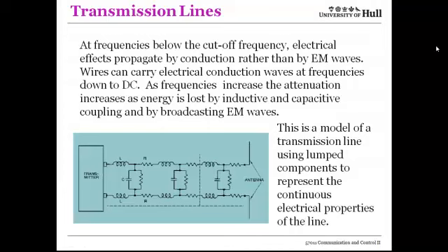Electromagnetic signals can propagate in one of two different ways. Either we can be dealing with an electromagnetic wave like light or a radio wave, which can propagate best through a pure insulator, or it is a conduction wave. It's a wave of movement of a concentrated area of charge, generally carried by electrons, and so you get a compression wave of electrons travelling along a conductor, and the more conductive it is, the better. Now at high frequencies, signals tend to propagate predominantly as electromagnetic waves through insulators, and at low frequencies they tend to propagate as conduction waves through conductors.